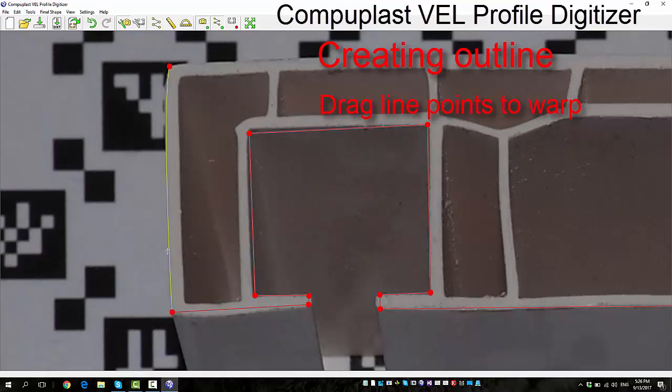Well, this outline is using Bezier splines, so editing of Bezier splines is always based on these directions, which you can adjust. You can adjust either these vectors, these positioning lines, positioning points, or you can just drag a certain point and align it with the shape.